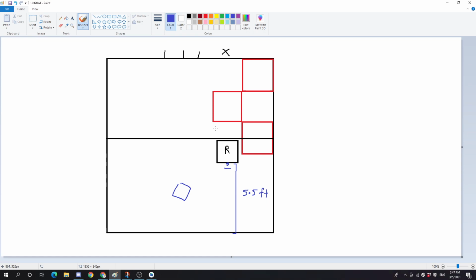We're going to disregard the turning aspect for this tutorial. There's going to be something separate on that since that's a topic of its own. It's more math involved. But shooting and adjusting the power based on either something relative or absolute is going to be covered today. Again, we're using a distance sensor, which tracks the distance relative to the back wall. But you can also do this with odometry.